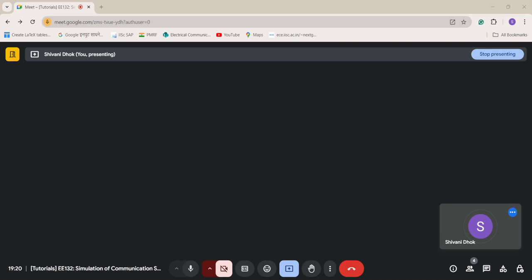Yeah. So now if you see, this is very close to a uniform distribution. And if you observe this particular PDF, it overlaps. So the analytical equation, whatever we had derived, is exactly correct. So this is how simulations generally help to analyze whether the derived analytical expressions of any problem in a communication system are correct or not. So now what we have done, we have done simulation of Z. We've derived, we matched the PDF of A, we matched the PDF of your angle.